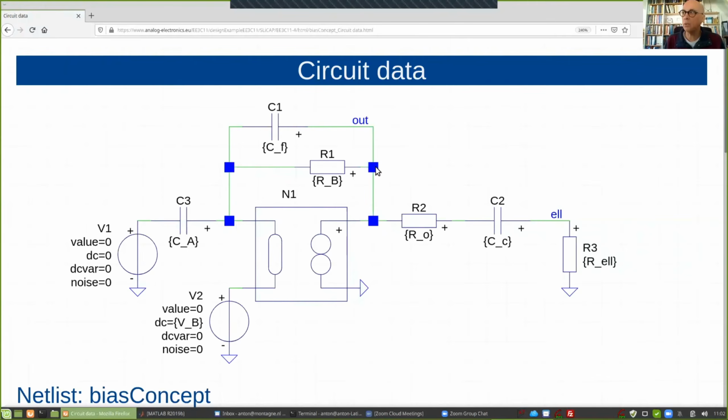Now, I know for this exercise, though I didn't discuss this with you, we need an operational amplifier with a very low equivalent input noise current. It will also need a very low input bias current, because the input noise current is associated with the input bias current. So we forget for the moment about any voltage drop, but of course we could make budgets for it, as I have done in the biasing example in chapter 5, I think.